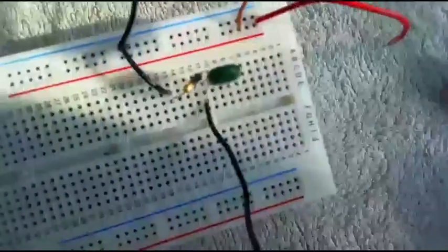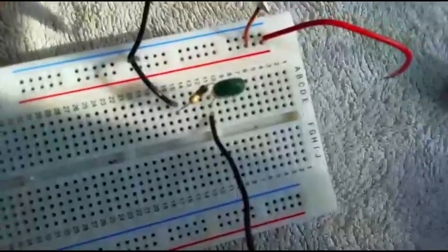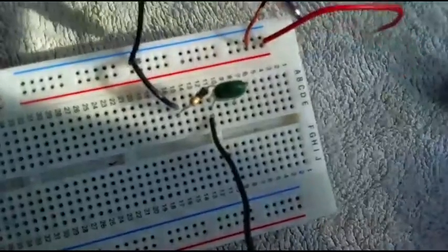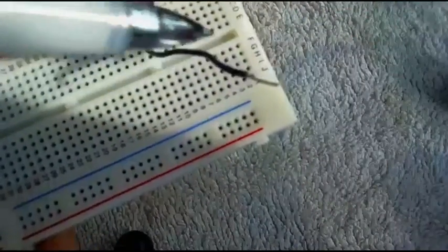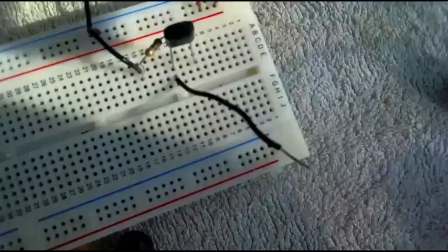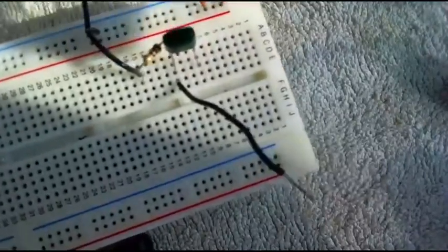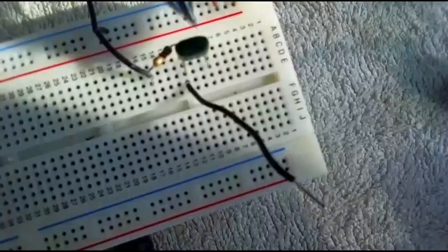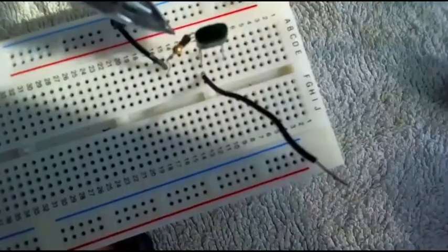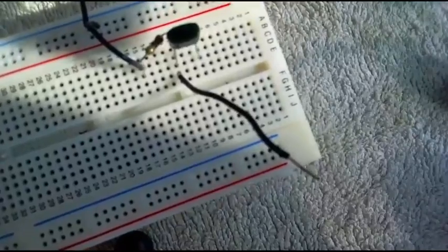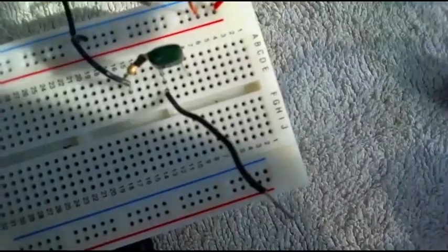and show my protoboard. I have a capacitor and a resistor, and then I'm going to bring in a signal on my power rail, and I have a measurement point that I've made that is basically between what will be a series of the various unconventional inductors and a capacitor. I'll use a different value for the different inductors versus this resistor. So I'm going to create a series resonant circuit with the unknown inductor and a capacitor, and then I'm going